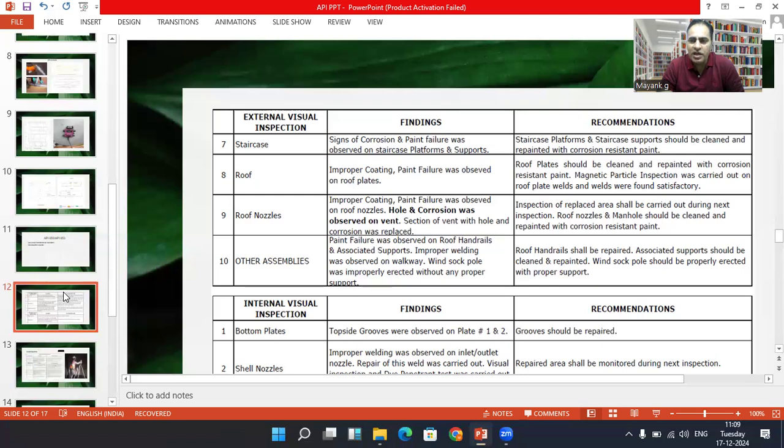These are the things that we cover under the staircase examination. In case any visual defects are observed in the staircase, then we go for a detailed checkup of the weld joints. For that, we use NDT techniques like the DP test. The DP test, as we covered in our previous video, is the dye penetration test, which basically uses three agents: first the cleaner, then the penetrant, and then the developer for the inspection of the weld joint.